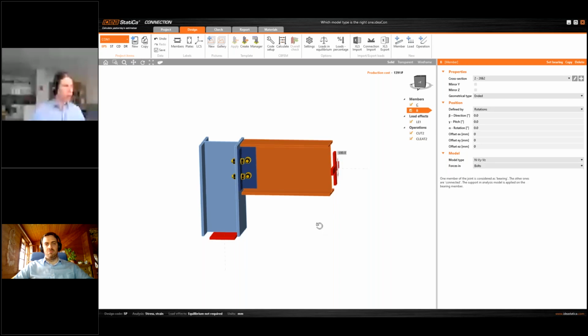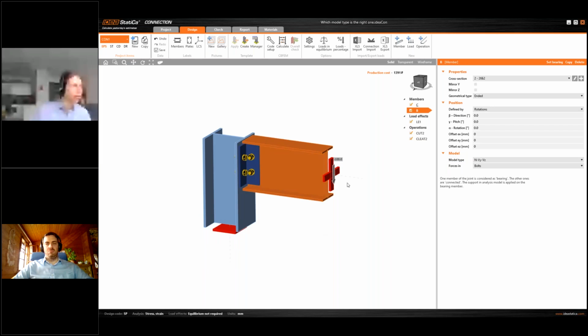And the last one, this means that this beam doesn't take any moment loading. So this is typical for, let's say, diagonals and wind bracings and so on. All these beams that are loaded mainly by tension or pressure. So that means normal forces and some shear forces.